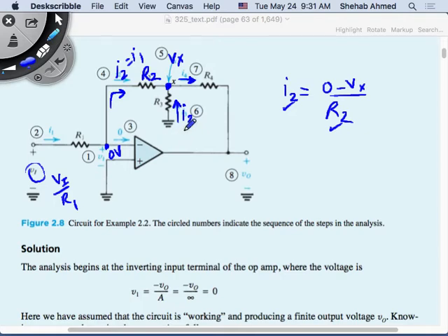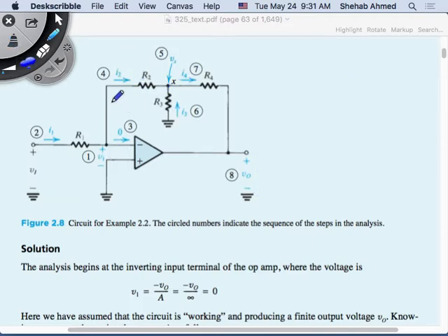And then if I have I2 and I3, I can calculate I4. You just sum them. So basically, I'm going to sum them up. What did I do? I was able to increase I4. Remember, V output is equal to this voltage drop plus Vx, so it's highly dependent on the voltage drop across R4. Then you can find V0. So I amplified it somehow using this modification of the circuit. Since you know I4 and R4, if you multiply them together, you can find V0.